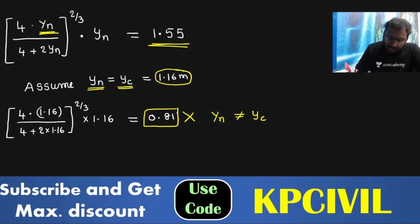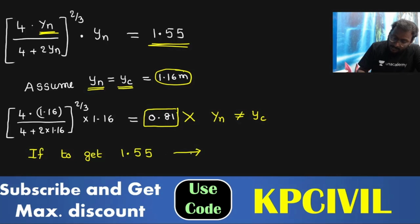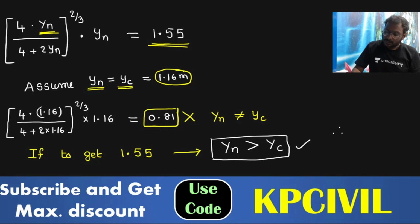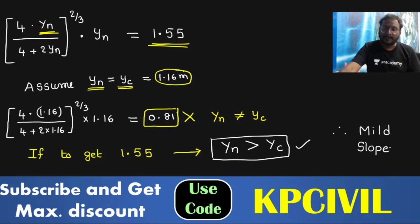So to get 1.55, what should be the yn value? Yn must be greater than yc. If yn is less than yc, you won't get 1.55. Only if yn is greater than yc will you get this. So what is the slope when yn is greater than yc? Mild slope. So the answer is B.